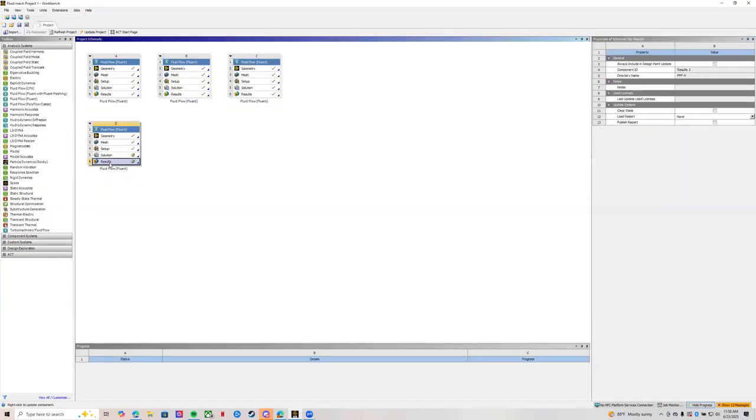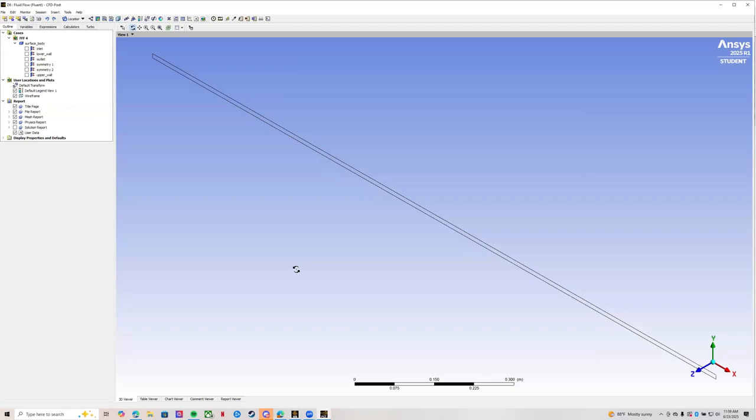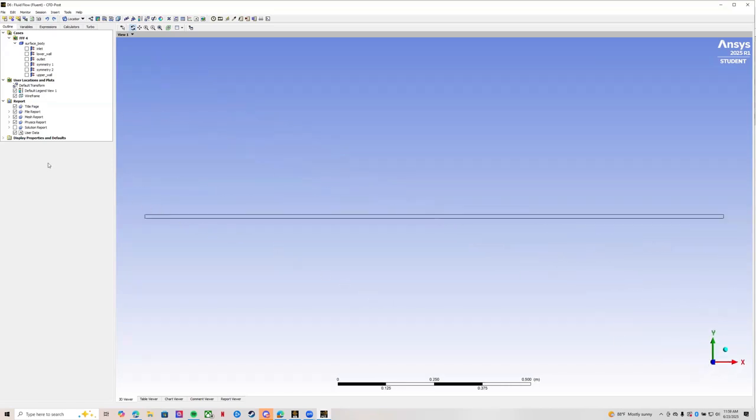After that's done, we can go ahead and click on our results portion. Here's where we're going to do our vectors, contour, and our chart to get that velocity profile. First things first, going to go here. We're going to insert indicator lines for the requirements for the midline and end line. And they're just going to be at the halfway marks for each.